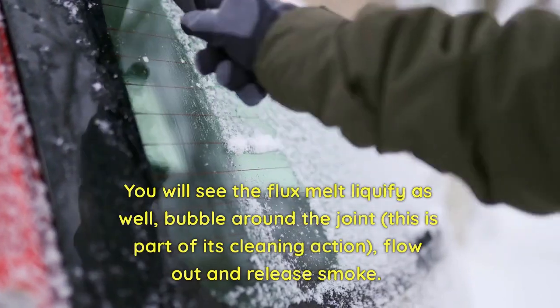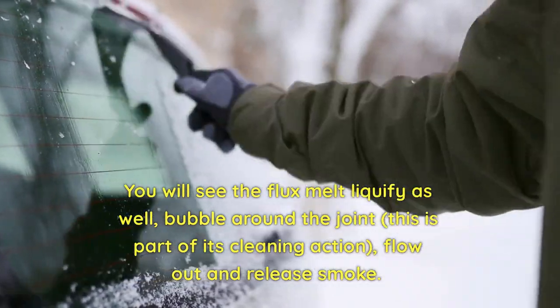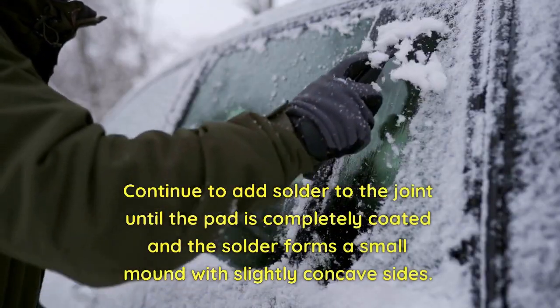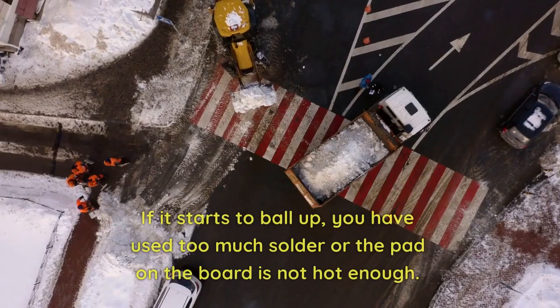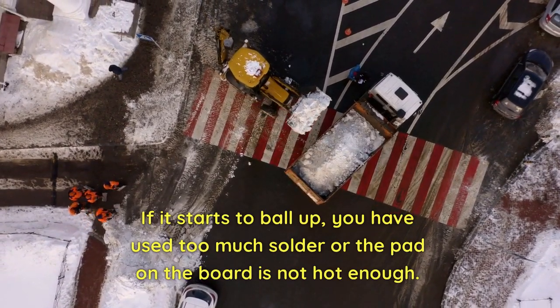You will see the flux liquefy as well, bubble around the joint. This is part of its cleaning action, flow out and release smoke. Continue to add solder to the joint until the pad is completely coated and the solder forms a small mound with slightly concave sides. If it starts to ball up, you have used too much solder or the pad on the board is not hot enough.